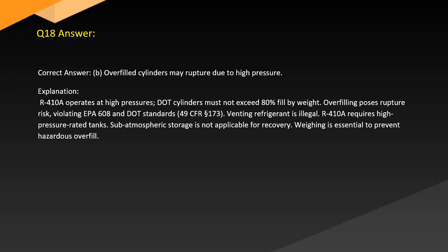Answer. Correct answer: B. Overfilled cylinders may rupture due to high pressure. Explanation. R-410A operates at high pressures. Cylinders must not exceed 80% fill by weight. Overfilling poses a rupture risk, violating EPA 608 and DOT standards, 49 CFR.